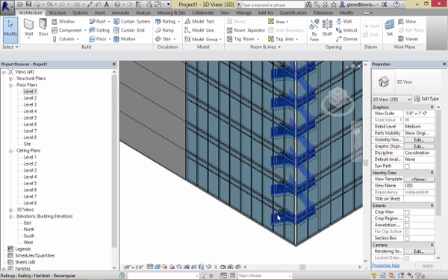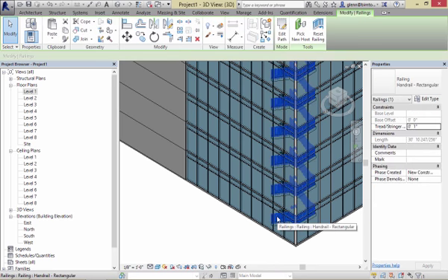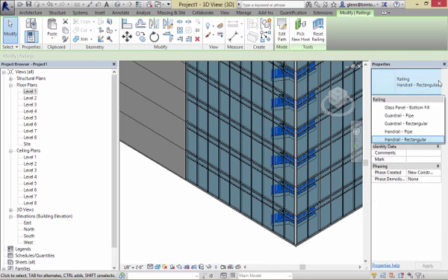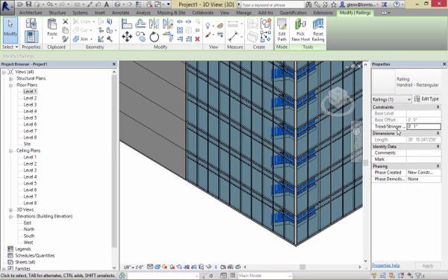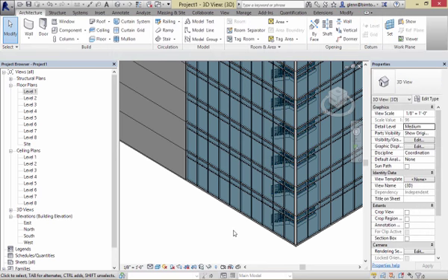The nice thing about this stair is it's the same sort of thing. Here's the stair. If I decide I don't like that handrail and I want to put the pipe rail in, I can do that. It'll just change it for the entire stair. It thinks of itself as one big object, which is pretty good. So getting a multi-level stair actually is pretty easy to do just by going up to a higher level. This will work as long as the floors are the same floor-to-floor height.